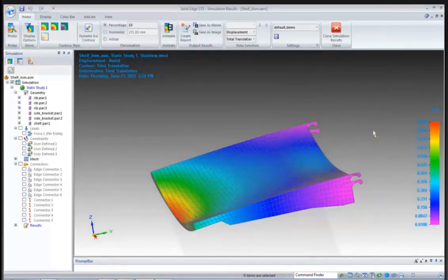So this brings me to a good point here. Because our stress is so low and our displacement is so low, remember our requirements were that it had to be less than 6, and it's under a millimeter, and our stress is really far under our yield. That's my new engineering term, really far. So what I want to bring up is that a lot of people out there are making stuff that they've been making for years, and they're like, well, it works, it's great. Well, that's great, but you could be saving a lot of money because you've over-designed it and you don't even know it. When you under-design it, you know it because it fails. When you over-design it, you don't know.